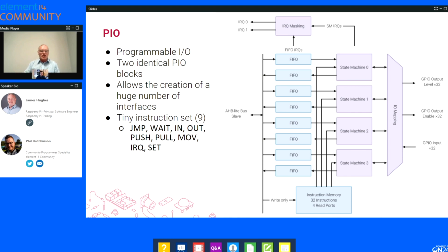So, for example, we can actually output DPI from a PIO. You use a couple of the state machines to drive it, and we can get 360 megabits per second out of PIO, deterministic megabits per second, during the active scanline periods, that's running from a 48 meg system clock. So in this particular DPI case, and all these are available as examples in our GitHub repos.